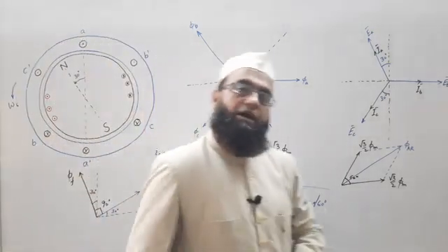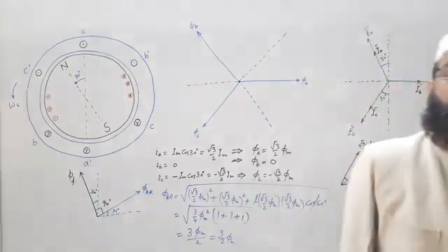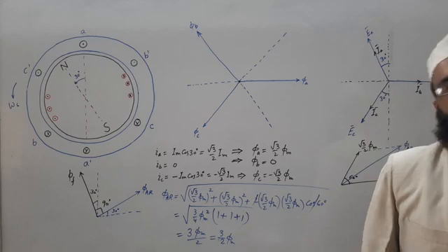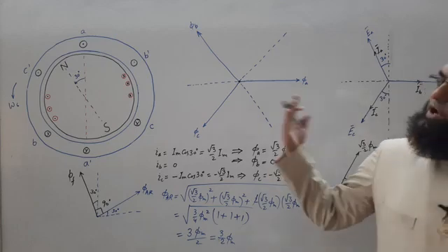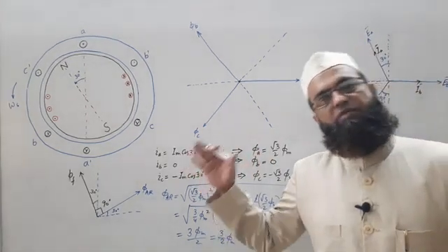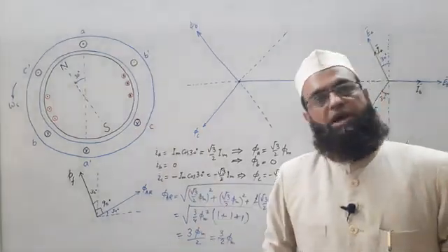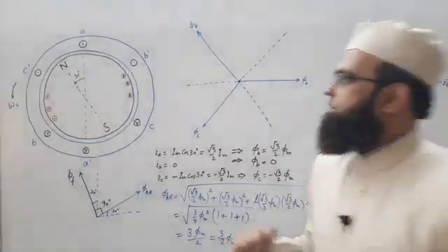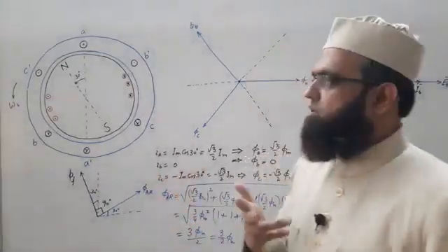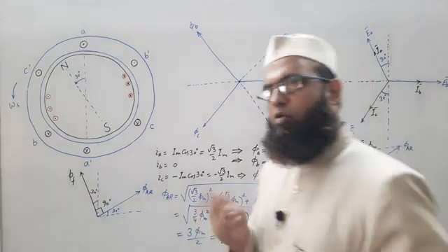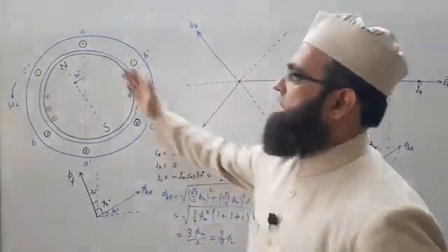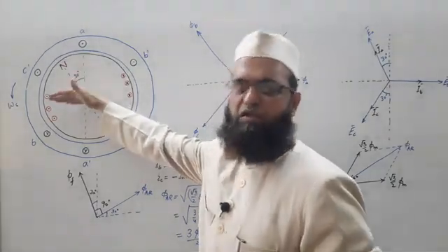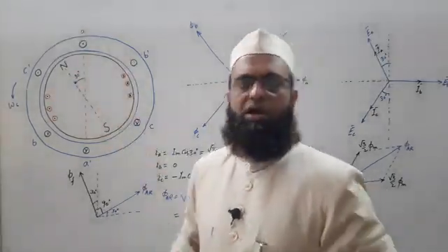That is phi AR, resultant armature flux, is again lagging with the main field flux by 90 degree. So in the two cases, previous moment and this moment, we can conclude that. You can check for other cases also. You can just take as your home assignment or like that. I am not asking you to submit it, but for your notebook or notes or practice, take some other moment like 60 degree, 45 degree, 90 degree or whatever you want, wherever you want, just check.